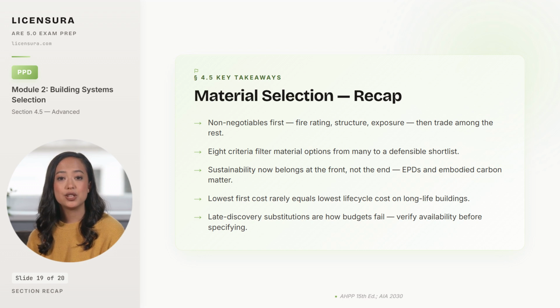Lifecycle cost almost always beats first cost on long-life buildings, and the architect should be the one making that case to the owner when VE meetings try to strip durability. And verifying availability before the spec is finalized prevents the late discovery substitution that kills schedules and starts the lawsuits over delayed delivery.